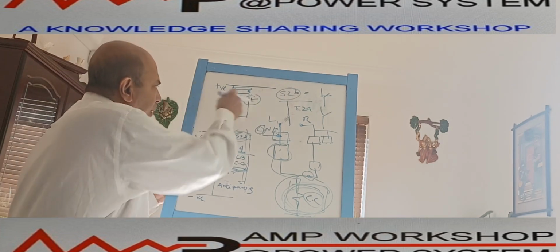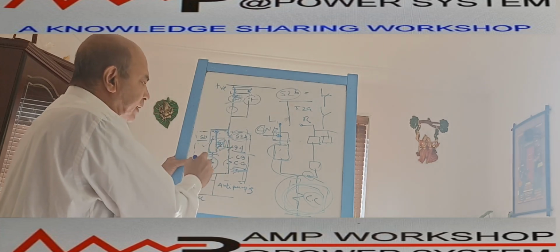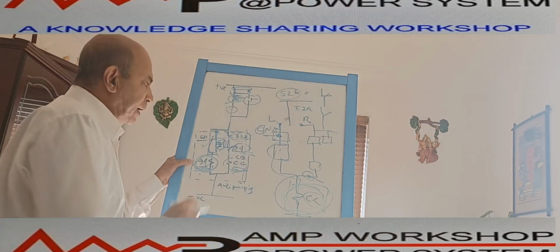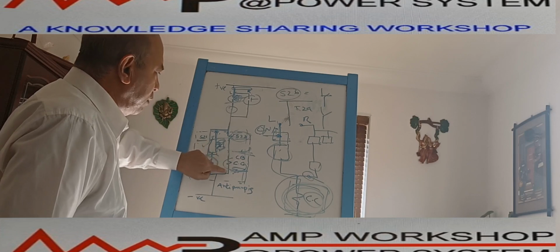But if you maintain pressing the push button continuously, then what will happen? It will close the breaker, right? The moment it closes the breaker, this will happen. The anti-pumping relay picked up. Immediately the anti-pumping relay is sealed through this. The anti-pumping relay is energized. So what will happen? This contact becomes open. So even if you maintain the command over here, as this is open, the closing coil will not get power. But if the anti-pumping relay is not there, then what would happen? You see here, suppose this is the breaker NC contact, right? So the moment you give the close command, immediately through this contact, the coil will get energized.